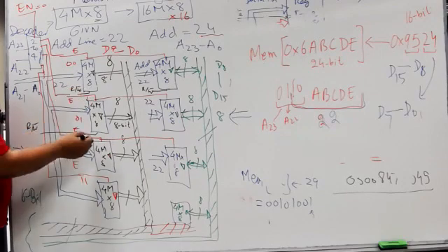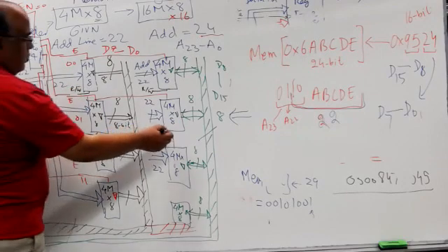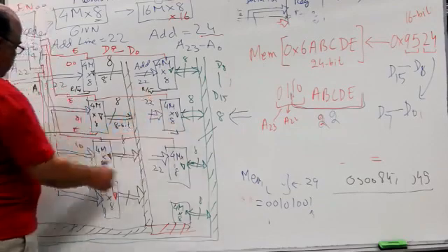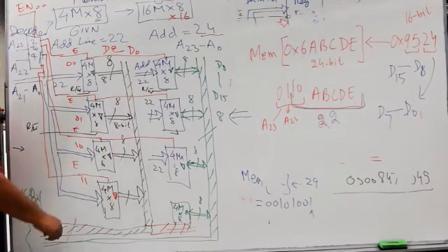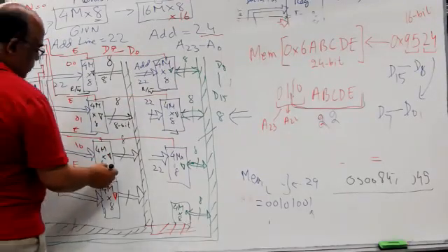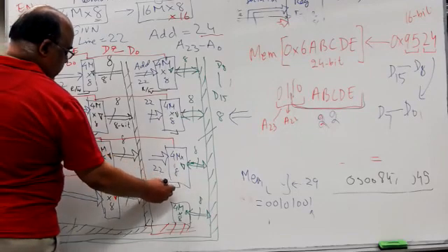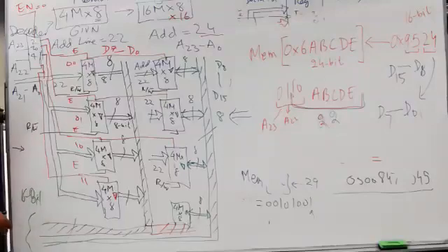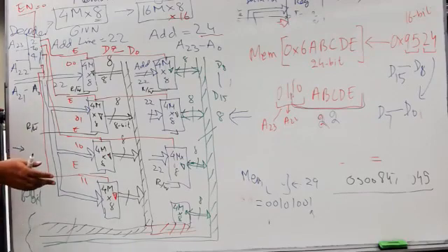Remember read/write will also be there with ROM. I don't draw read/write because it gets very messy. I just write with a star that read/write is going to all the ICs. This read/write comes from the processor. The processor has this data bus, address bus, and read/write.